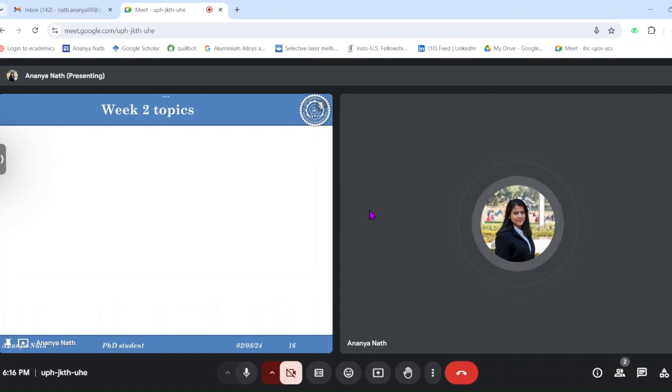The next thing is triangle sorting. So maybe I can show you here. Triangle sorting is like, if this is my triangle, this is my triangle, this is my triangle, and this is my triangle, this all comes under indirect slicing, where we take the STL file where the whole object is made with small triangles, and using the coordinates of the triangles, we make the coordinates of the sliced path, and then we slice the whole object. This is the idea.